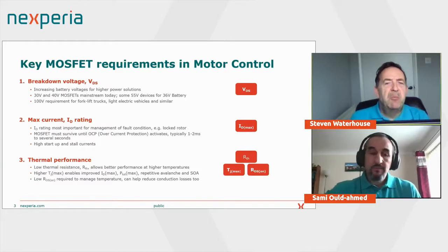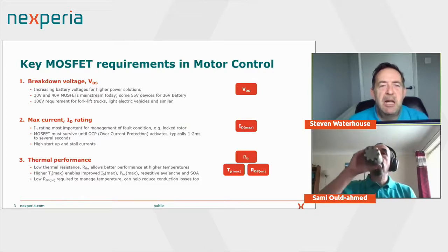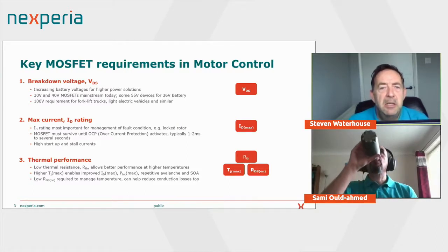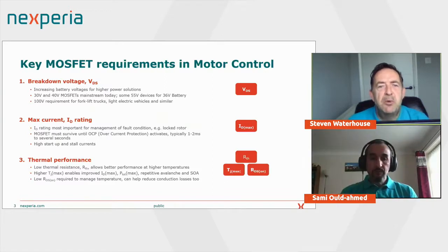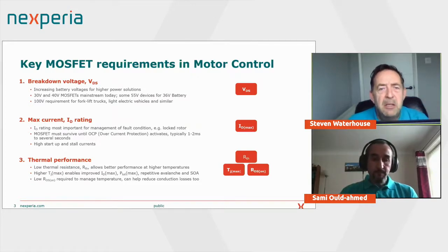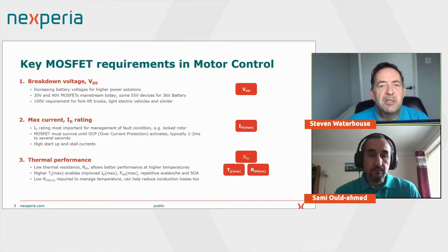Okay, so normally the battery management device can either be two MOSFETs back to back, or it can be one MOSFET as an isolation, like a load isolator. If you imagine there's some inductance in the circuit, and a lithium-ion cell can supply an infinite current for a very short period of time. This is why lithium-ion is a very effective energy transfer system. So you may have currents in excess of 300 amps for maybe up to 10 milliseconds.